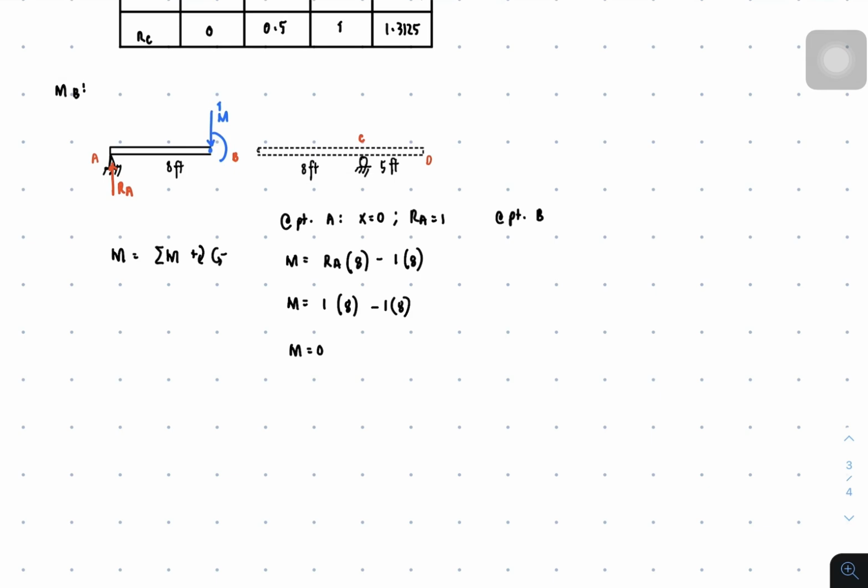So we will only be having one value of moment. The reason, you know already, is that whenever we go back to the shear and moment diagram, for the moment diagram you will have two values of moment whenever there is a moment load, like an external moment load. Then you will have two values in your moment diagram. But since our load is only a vertical load, we have only one point value at every point A, B, C, and D, unlike in shear.